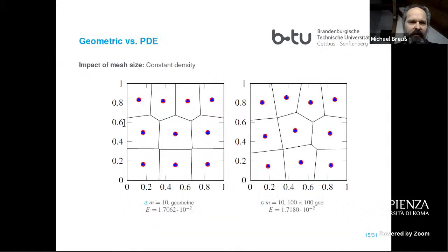So now this is the impact of the mesh density. We have two experiments. The first experiment is with 10 seeds for generators. The second series of experiments, I'm sorry, will be with 20 seeds of the generators. Let's have a look at what happens. To the left is the geometric solution, which is kind of the ground truth that we trust, and we would like to have a similar result with the numerical simulation using the Eikonal equation, and we look at a series of mesh refinements.